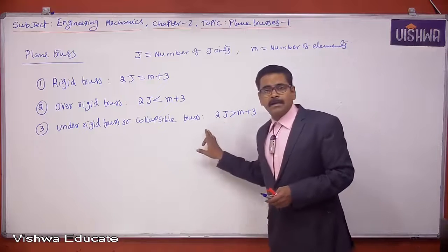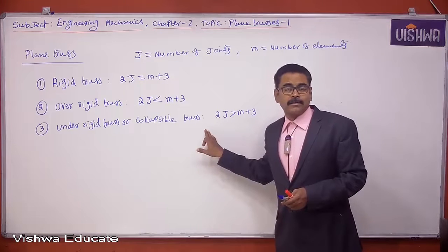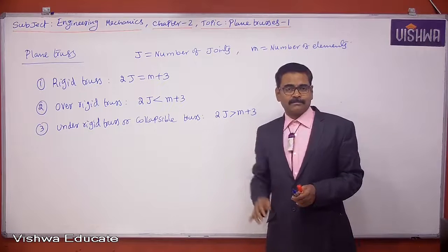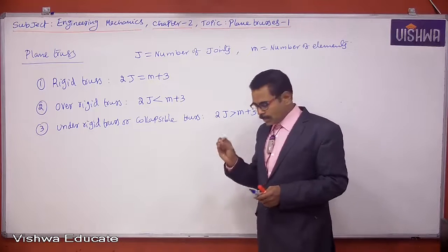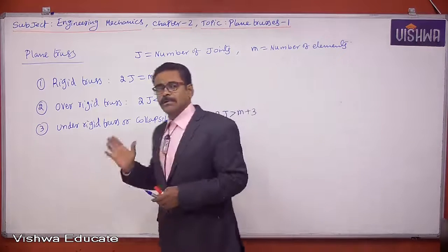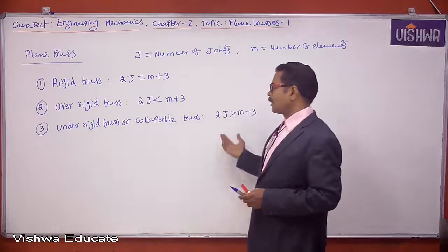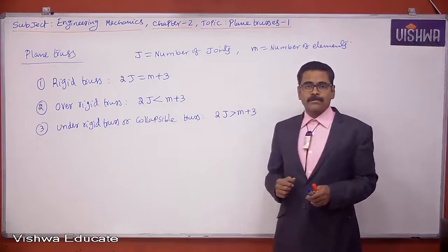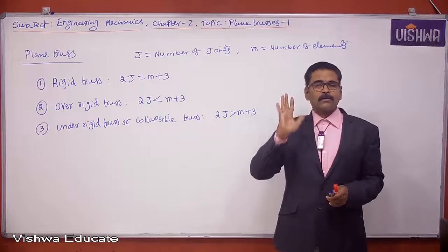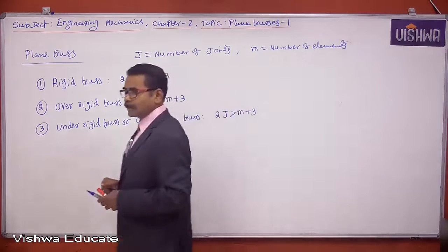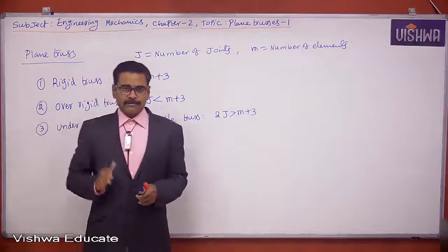If you apply any external load on an under rigid truss or collapsible truss, immediately the truss will collapse. So an under rigid truss or collapsible truss cannot carry any external load. We never design any under rigid truss or collapsible truss.